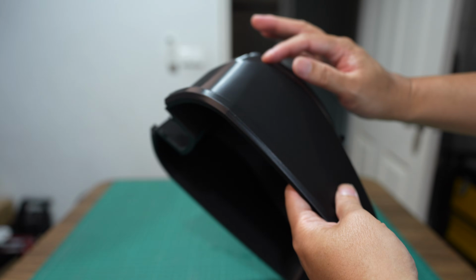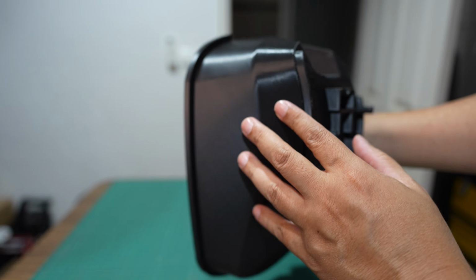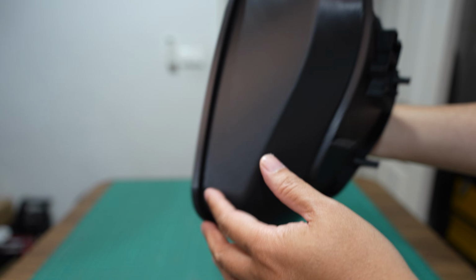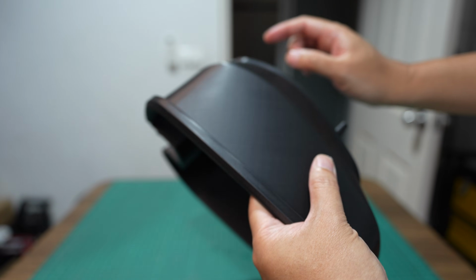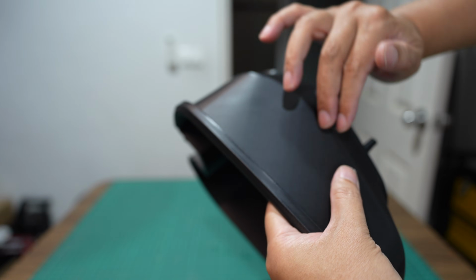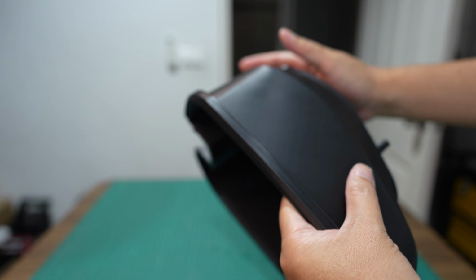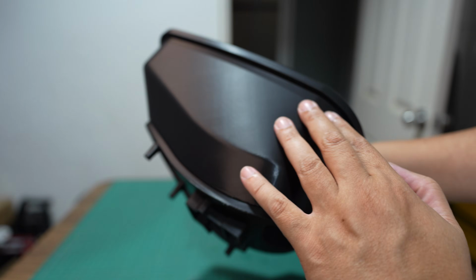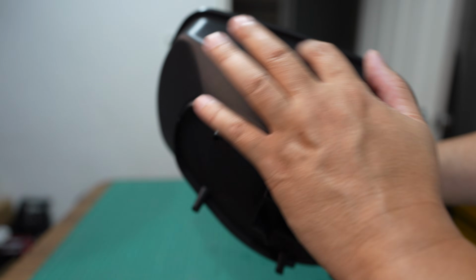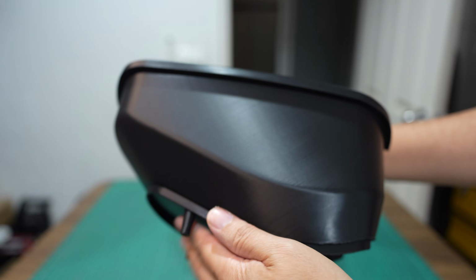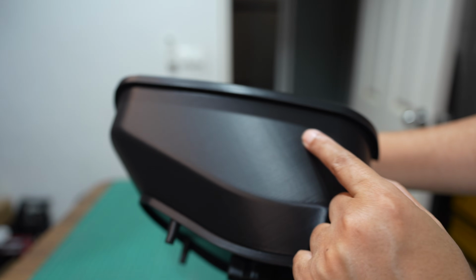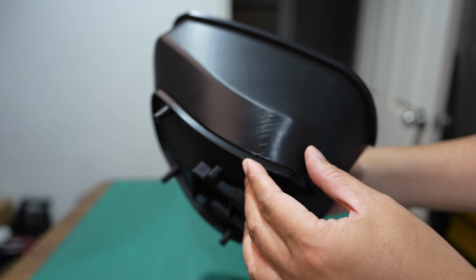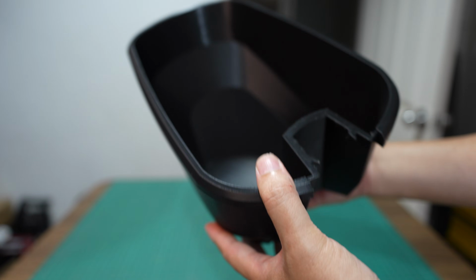One thing I noticed with the new firmware update on the Creality K2 Plus, the ringing is gone. See here, usually I will see ringing from the high-speed printing, but now it's gone. Very smooth. I cannot see even one single ringing. Very small, faint ringing line, but a lot less than the former firmware version.